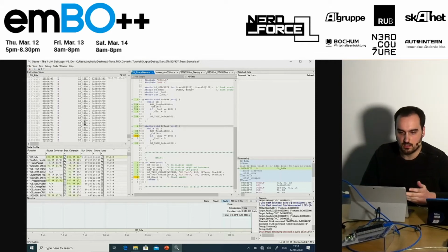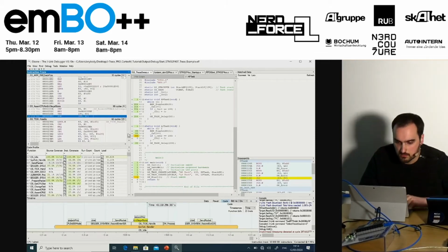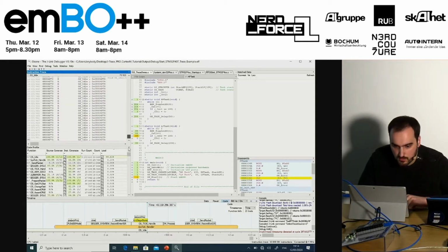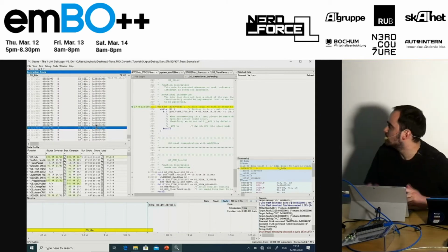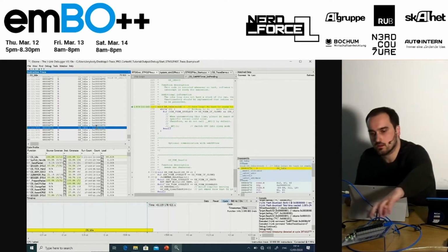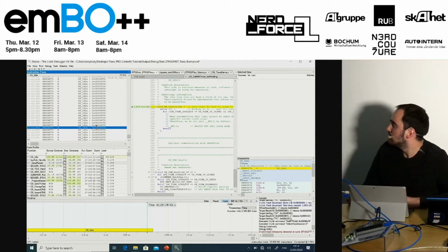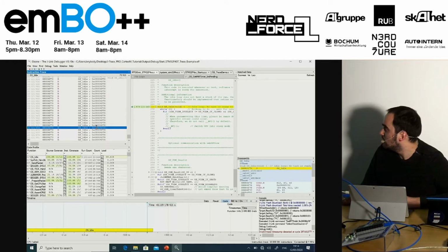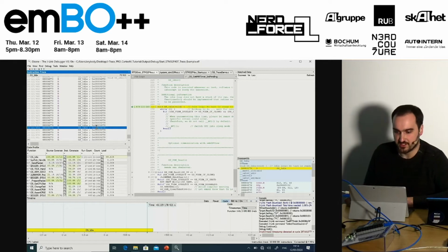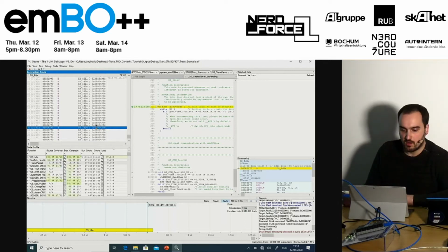As you now see, we are mostly, oops, where did I jump to? There we go. We see we have a couple of branches because this is a simple blinky LED application with 2 tasks running on the RTOS, and most of the time we don't blink, so we're idle. So that's why we spent a lot of time here.